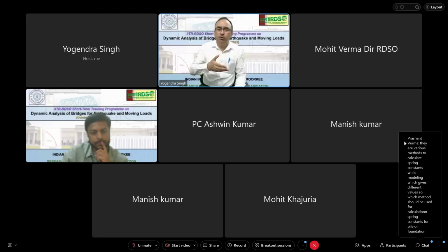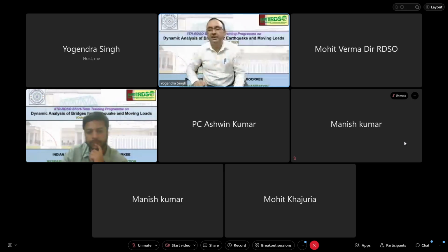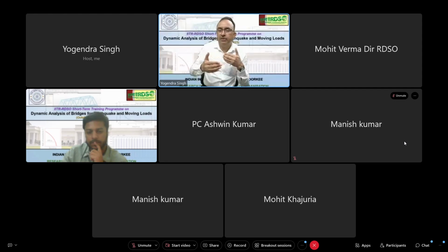So we can model it using a gap element where we can define the gap equal to the gap between the superstructure and the stopper, and then it can be assigned a high stiffness. So one thing is its high stiffness, which we have to take into account. Another is the impact, because there will also be impact. So generally, the impact modeling, which is quite complex, we ignore, and we consider this by having an element which has almost zero stiffness till the two come in contact, and after that the stiffness increases significantly. So this type of analysis we can use for modeling stoppers and shear links.